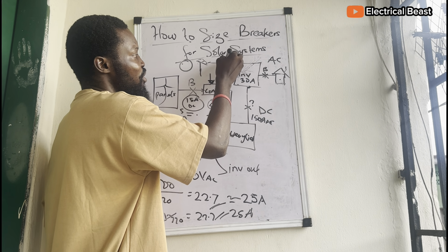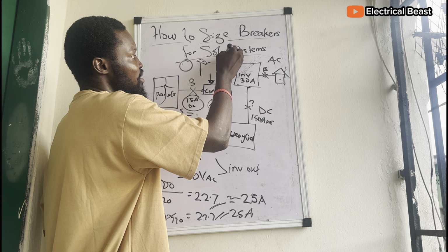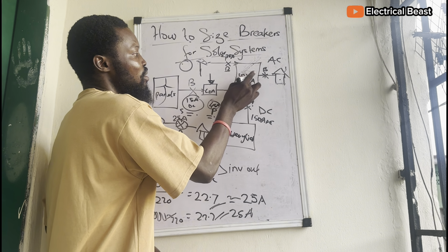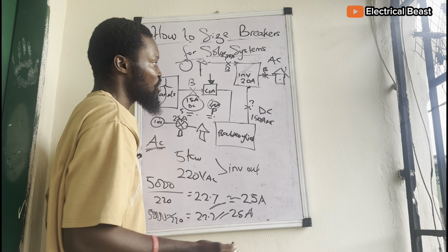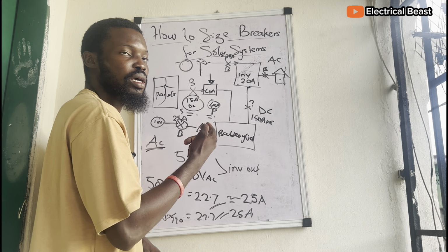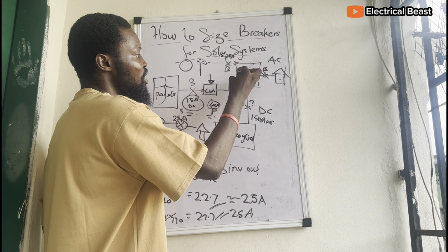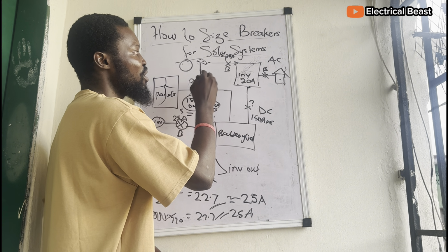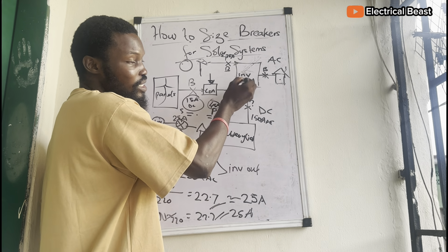So for this breaker, you might want to use, let's say, about 35 amps or 40 amps thereabouts. So if it's 20 amps, you can set to 20 amps. You don't want the inverter to consume a lot of energy from your meter, so set it to a very low amperage for charging. So you're going to use the breaker according to the settings for your inverter.